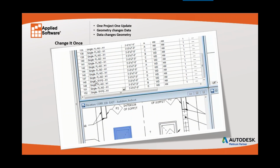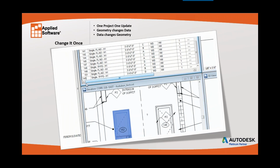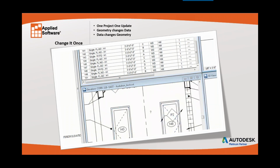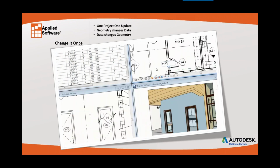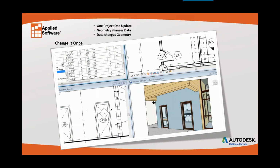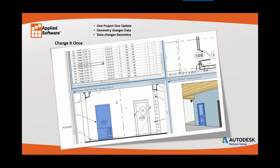Notice here 142. I'll change it to a different type of door to match both of these. When I do that, it makes the change here. For example, in the floor plan in the schedule, I change it to door 151 and it'll change. Over here to door 148, 143, B, and the top one I think I'm going to go ahead and change that as well. You'll notice the elevation changes to 143B as well. And there's A and B. Now I can simply swap out that door for a different door style, just like that.